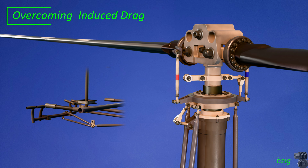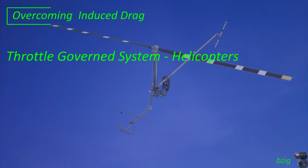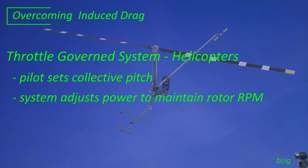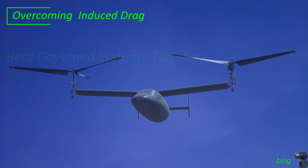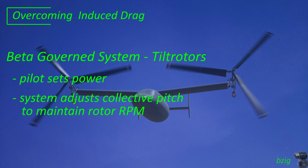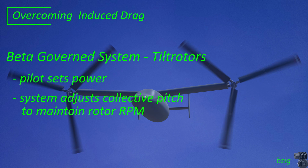I'll segue here briefly to mention tilt rotors. The type of system I just talked about is called a throttle-governed system, meaning the pilot sets the collective pitch of the rotor blades, then the system adjusts the throttle in order to maintain rotor speed. But all of the tilt rotors I'm familiar with use what's called a beta-governed system, meaning the pilot sets power and the system then adjusts the pitch angle of the blades. Beta is what engineers call blade pitch angle.